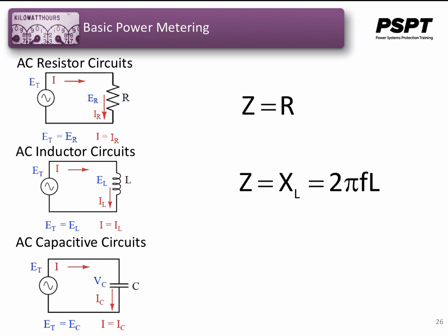Since capacitors conduct current in proportion to the rate of change of the voltage, they will pass more current for faster changing voltages as they charge and discharge to the same voltage peaks in less time, and less current for slower changing voltages. What this means is that the reactance in ohms for any capacitor is inversely proportional to the frequency of the alternating current.